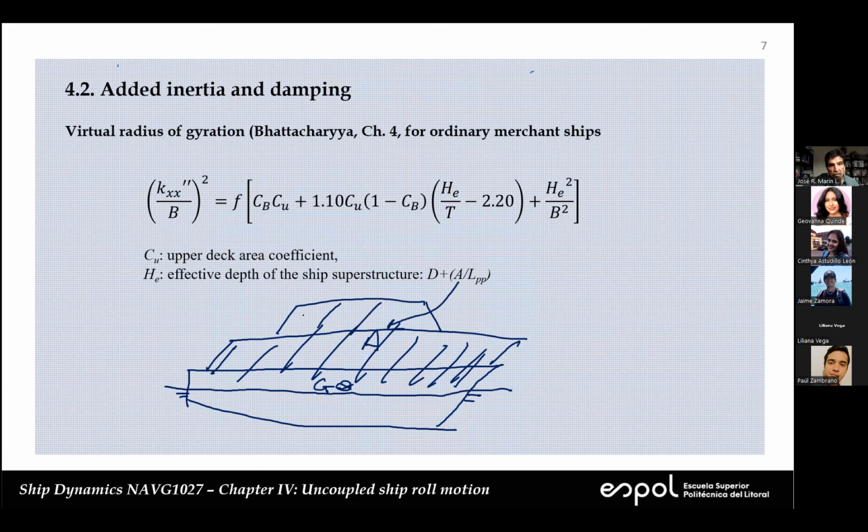This is just another way to include this material in order to calculate an effective depth of the ship, and that goes in here. You see that when you include this, it is going to increase. This is a large procedure. There are some options for this value of F in that reference. The CB, block coefficient, is no big thing. This is draft, and this is beam, of course. So this is specifically for these ships.